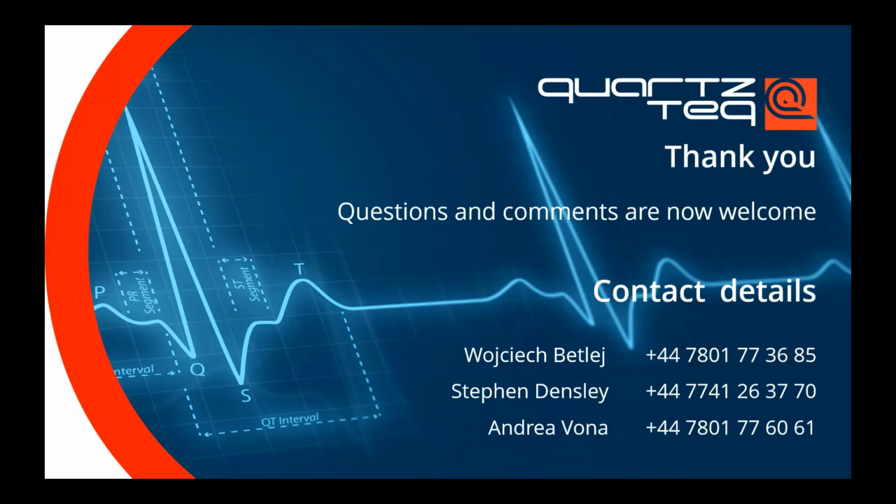So we treat every start like between 20 to 30 working hours. Usually your maintenance regime is determined by the number of working hours. So when you assume that you remove retaining rings on every major overhaul, the number of starts and stops will shrink the time or distance between two major overhauls. Therefore, I would say you should do it more often. But again, treat a start and stop as 10 to 30 hours of running of your machine. That should help you.